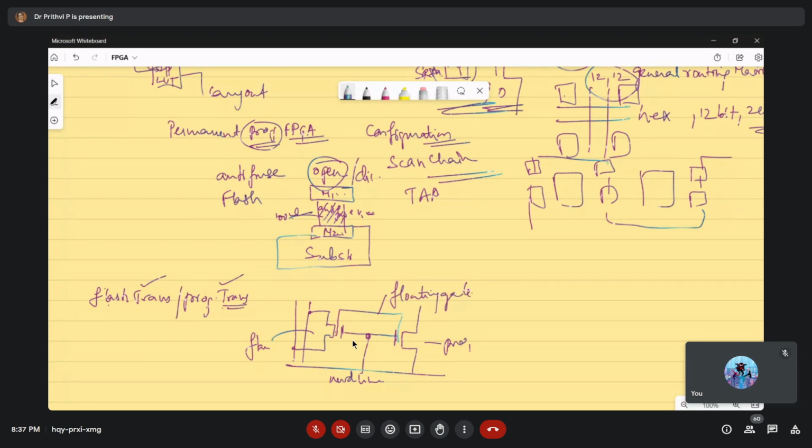Okay, this is something like a high quality programmable read-only memory, the flash FPGA. It uses the floating gate structure, which holds charge in capacitance format. There it will store some leakage charges, and that will control the gate of the transistor. So this is very sensitive, where at the connection points in between, read and write operations have to be performed based on the gate potential available.